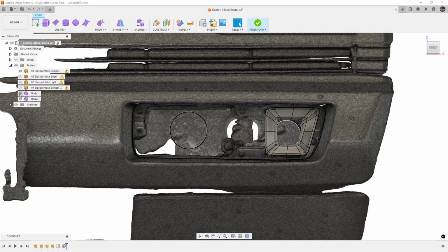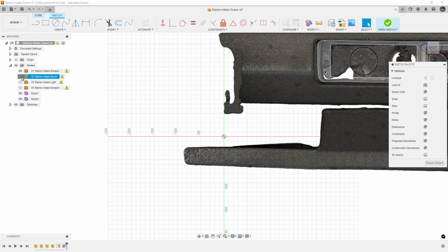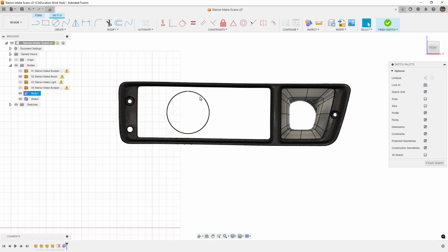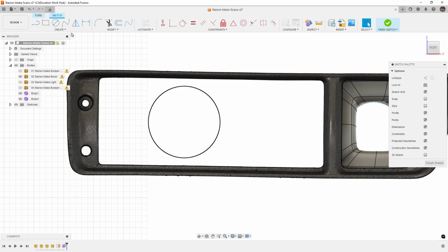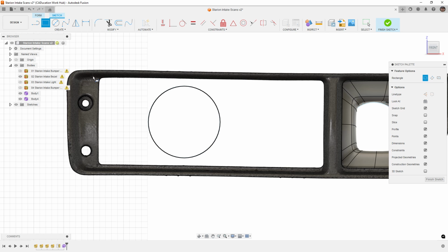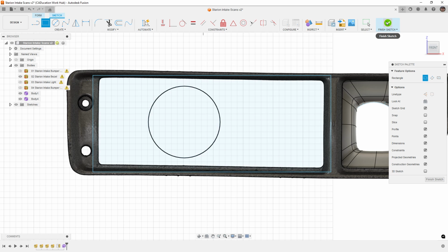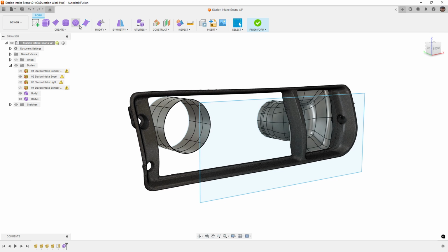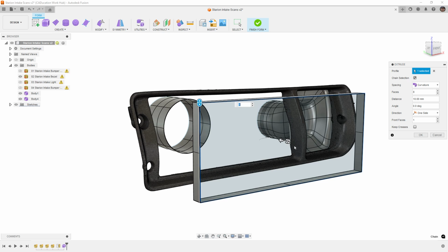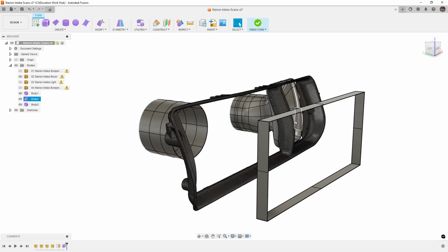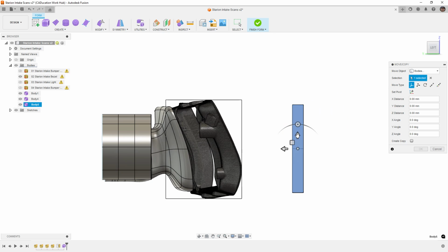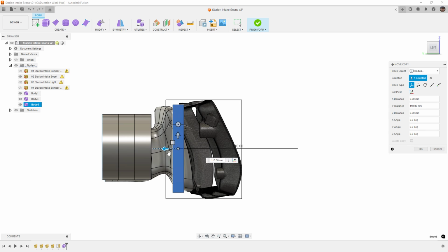All right, so we've got this piece here, and again, what we're going to do is create a sketch. Just create it on here. And turn the bezel on, and this one's easy because it's just a rectangle, so I can come up maybe right there to right there, and then we can just extrude it. So same thing, last one was 10 millimeters. That's where I'm going to start. I'm going to select it, use move copy, so M. Just going to kind of move it into position.